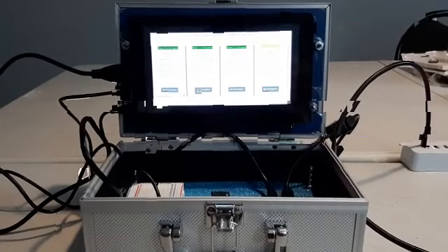The voltage of this stepper motor is 12 volts. It comes from a power supply, which I have turned on. To change the damper set point, I click on this set parameters button here. By clicking on this parameters button, this window opens, and from this window we can define the temperature set point in auto mode, the damper opening percentage in manual mode, whether the vacant mode is activated or not, and if it is activated, the temperature set point in the vacant mode.